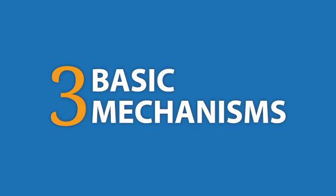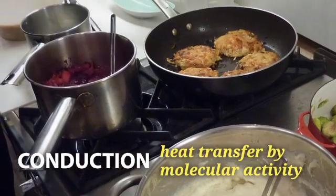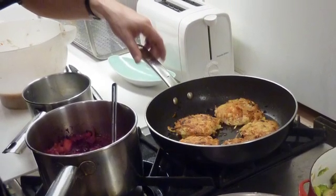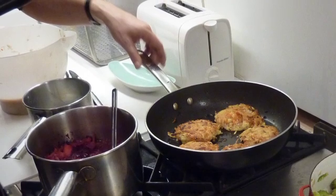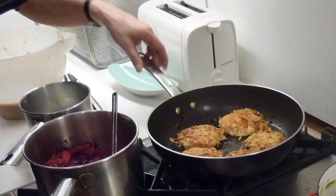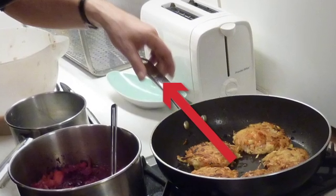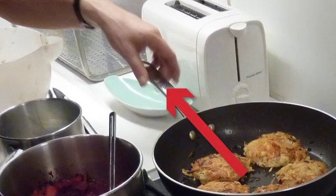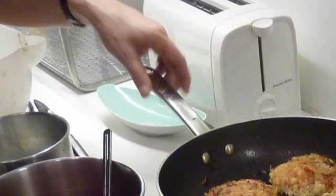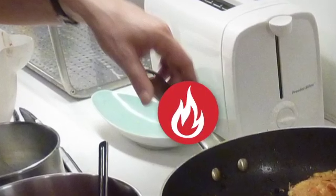There are three basic mechanisms for heat transfer. One is conduction, which is defined as heat transfer by molecular activity. Through conduction, heat can be transferred from one part of a substance to another, or it can be transferred between substances that are in direct contact. For example, when a pan is on a hot stove, heat is transferred from the bottom of the pan to the handle via conduction. Different substances conduct heat differently. For example, air and wood are relatively poor conductors of heat, while metal is a good conductor of heat. This is why you would get burned if you were to touch the handle of this pan.